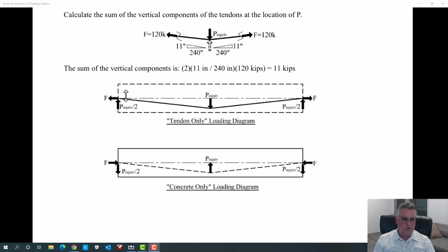You will have some stresses in the tendon, of course, because we put them there. We stress the tendons. There will be stress in the concrete that we just talked about. There will be some bending stress and some compressive stress. But statically, nothing is happening, and that's a tough concept. That's the concept that people struggle with and start battling with their fundamental beliefs of statics and equilibrium. But remember, these two things are canceling each other.